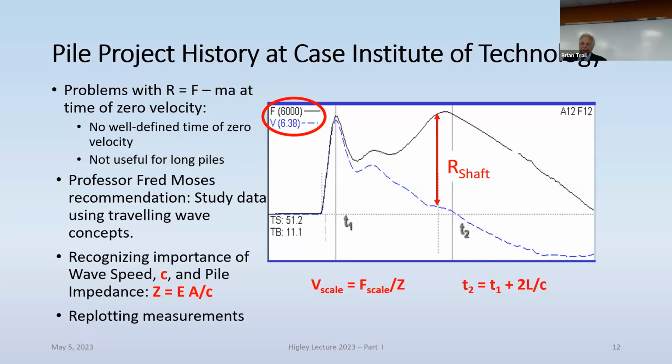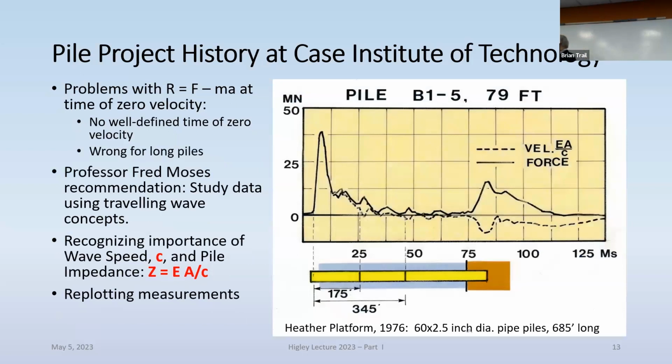And with that, investigating traces like here, this offshore trace where we had a long pile, made it even clearer what we saw. For example, here on the left side, until the point where the penetration of the pile in the ground was encountered, above that being water, we had throughout that proportionality between the two curves, and only a deviation of force from velocity where the pile penetrated.